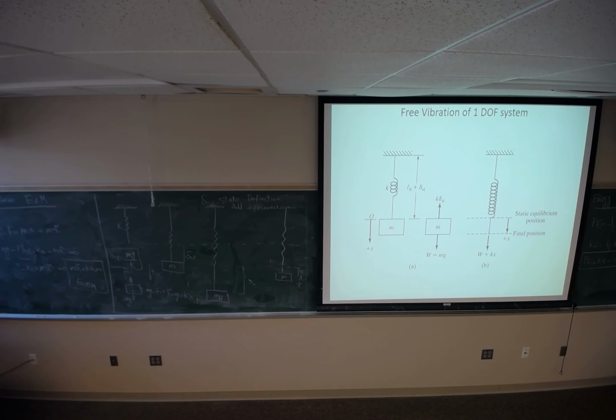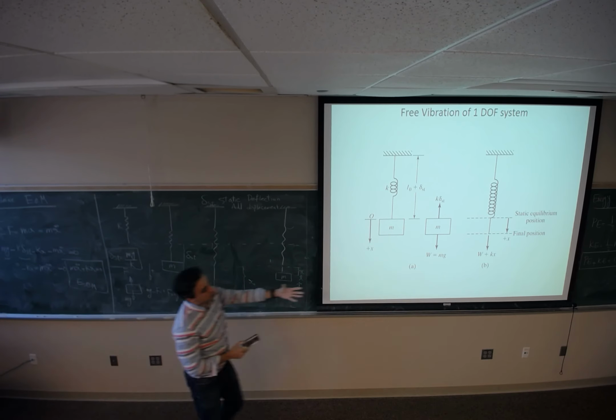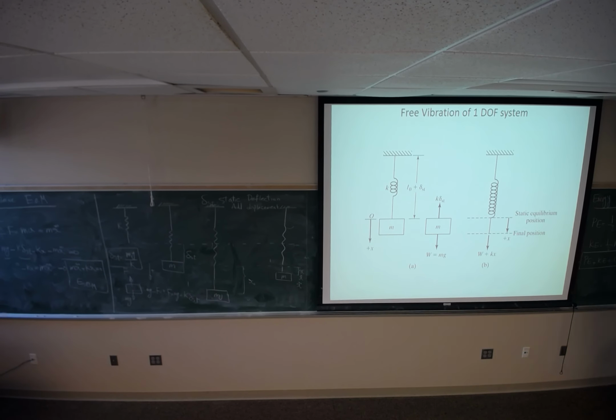Good? Now, since it's not changing with time, it's constant, if I differentiate this part with respect to time, it's not changing over time, so this part is going to be 0. So the derivative of potential energy plus kinetic energy with respect to time is going to be 0, if your system has no friction, that is, we don't dissipate the energy in the motion of the system.